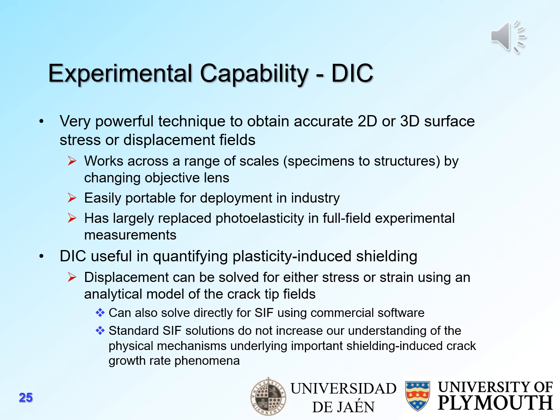And equally, the commercial software will solve directly for stress intensity factor, but then you are getting the inaccurate Irwin stress intensity factor. It's my thesis here that one of the things that's holding us back in experimental capability with DIC is that the standard SIF solutions do not increase our understanding of the physical mechanisms that underlie important shielding-induced crack growth rate phenomena.